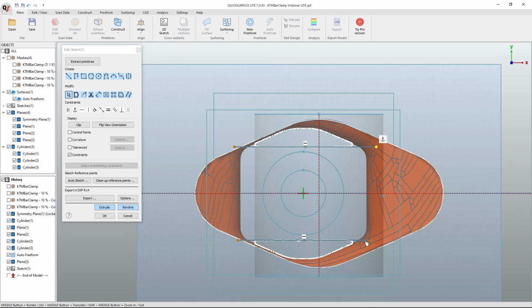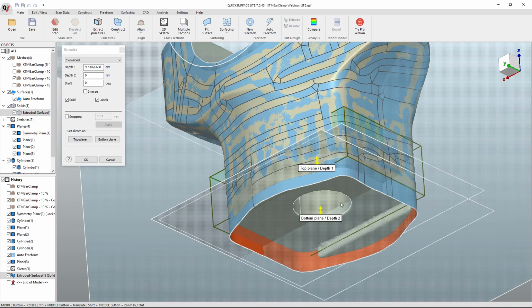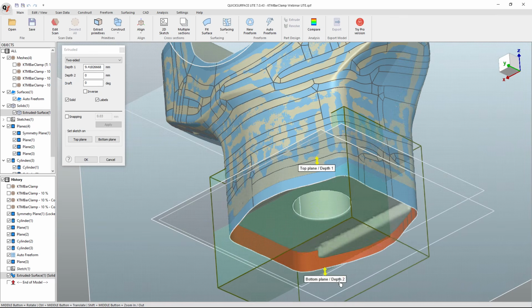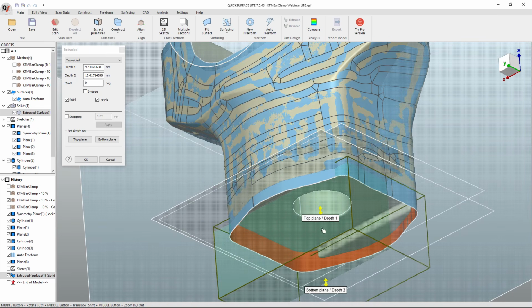And what this does is it gives me just the features I need, right? So I can connect those. I don't really care if this is square. All I really care is that we've extracted where those edges are. And what we can do is we can extrude that as a solid. So this is going to come down. This one will be 0 from that plane.